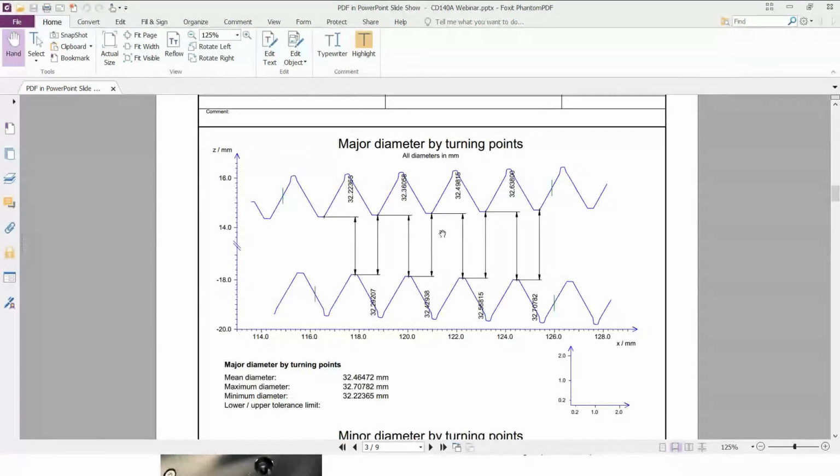So remember that in order to measure diameter, we have to have a twin stylus. So if you're measuring this with a single stylus, the diameter features will be omitted from the report, but it gives you all of your individual diameter results based on how many features you're able to capture within your measurement.